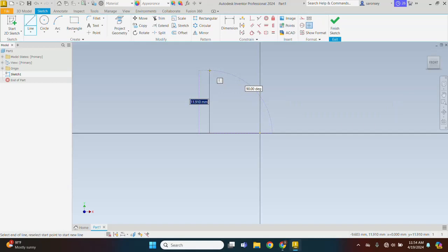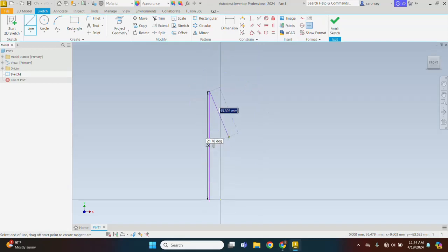and you can straight away specify the length of this line using the dynamic input boxes that are highlighted in blue and black. So let's say your line has a length of 100 mm. You type that 100 and press enter. Let's zoom in a little. Okay, so this is what we have.